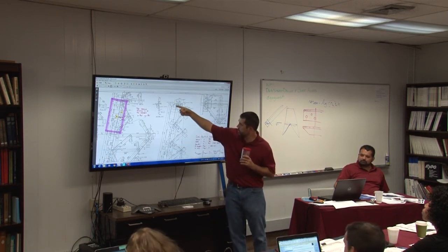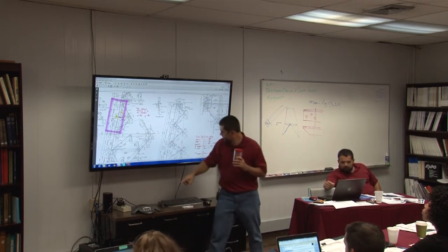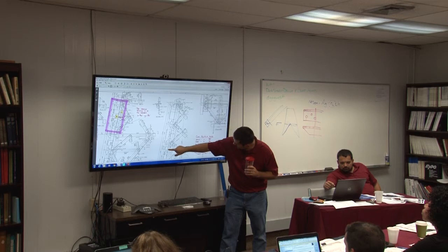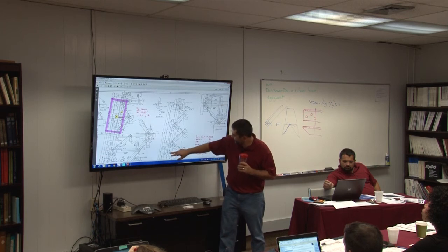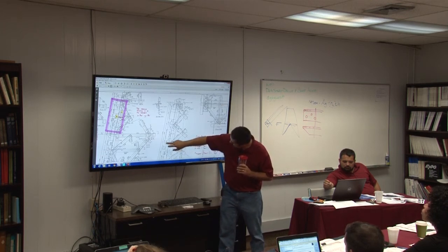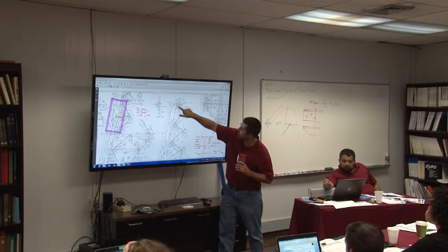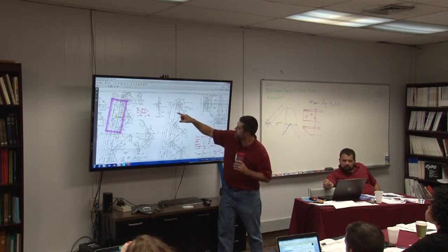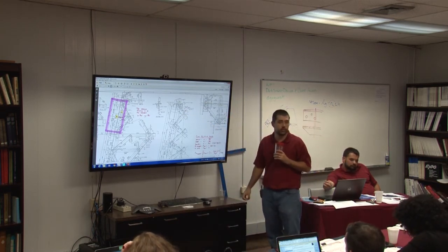So I'm looking at this leg member here, along this leg. And now it's not particularly clear. I don't have a situation like this, right? Here's 2 1/16. So this bolt and this bolt are 2.5 inches apart, and this one is 2 1/16. It's not drawn to scale, so you've got to be careful about that. But then I come up here and I'm looking at 1 11/16, 2 1/16, 2 3/4, 1.5. So here's probably the critical one right here, something through that path, because these 2 bolts are only 1.5 inches apart. So you can find that. Usually you can figure out which one to do pretty quickly.